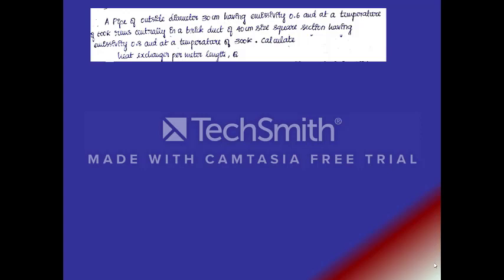A pipe of outside diameter 30 centimeters having an emissivity of 0.6 and at a temperature of 600 Kelvin runs centrally in a brick duct of 40 centimeter size square section having an emissivity of 0.8 and at a temperature of 300 Kelvin. We have to calculate the heat exchange per unit length of the pipe. Let us try to understand the problem.